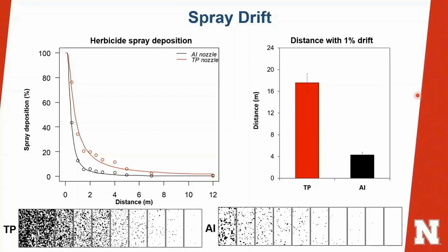So what we did there, we did these pesticide applications within our wind tunnel. We have a wind tunnel that is 40 feet long, so we can have drift stations at different downwind distances from the nozzle. So we can collect the drift deposition at different distances and compare them with different nozzles or different solutions.